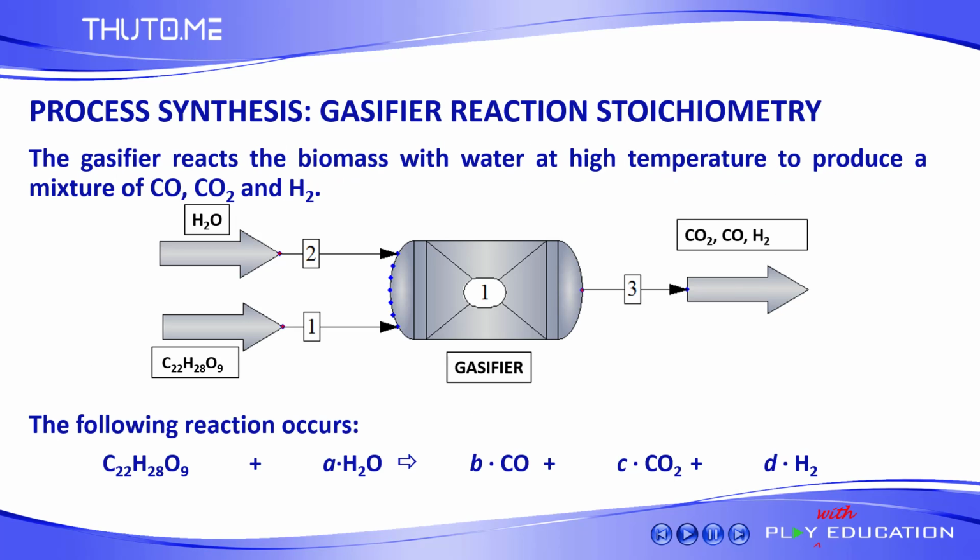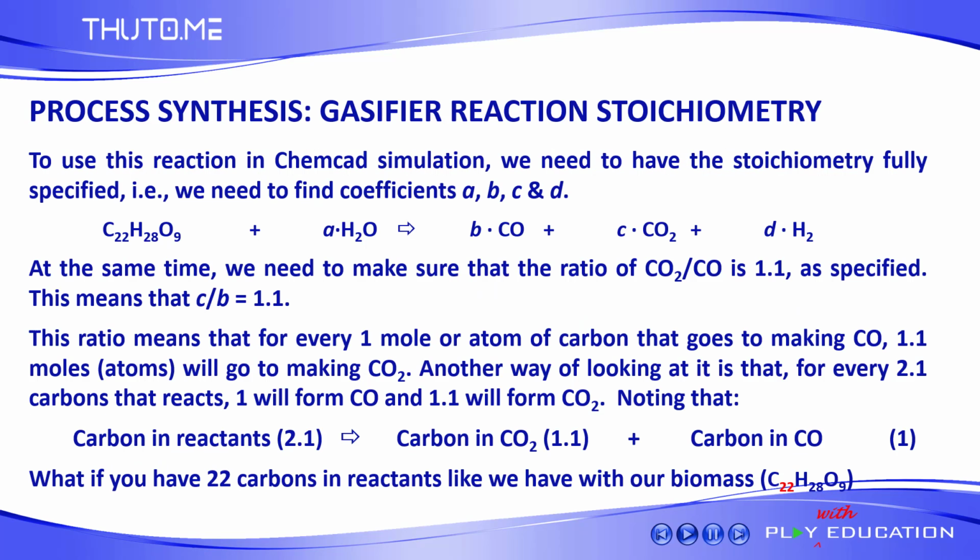Now, let us look at the stoichiometry of the gasification reaction. The gasifier reacts the biomass with water at high temperature to produce synthesis gas, which is a mixture of CO, CO2, and H2. The gasification reaction can be expressed as this chemical reaction here. To use this reaction in Chemcad simulation, we need to have the stoichiometry fully specified, that is, we need to find coefficients A, B, C and D.